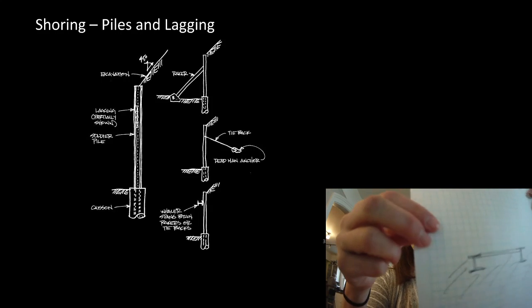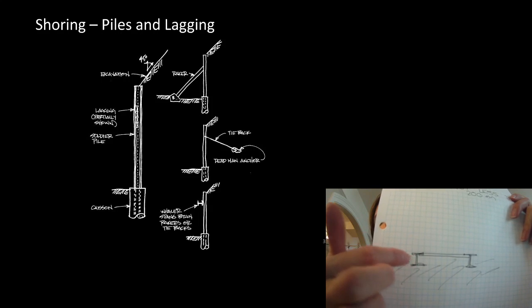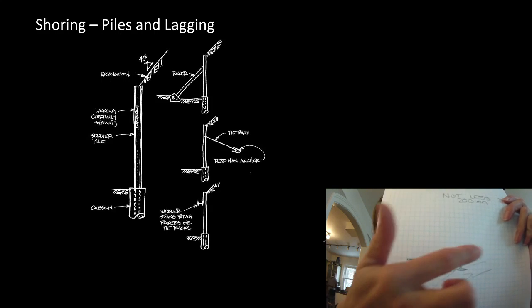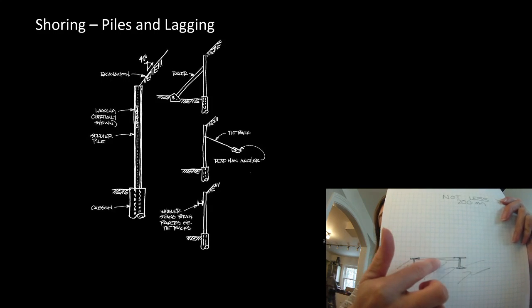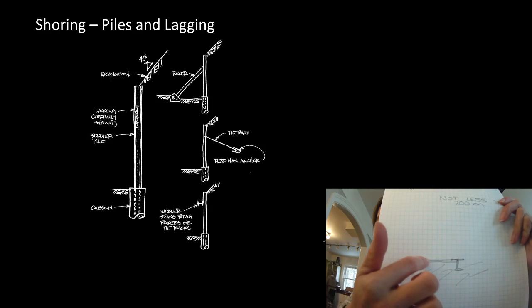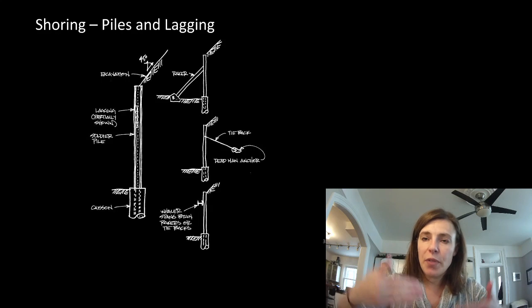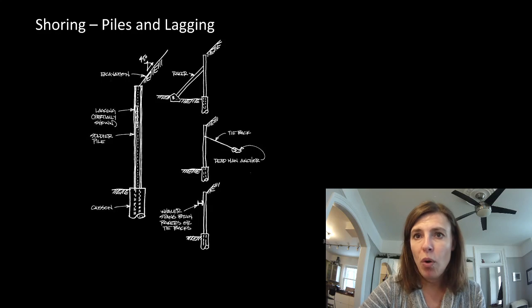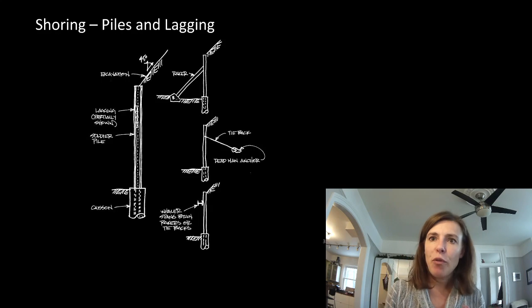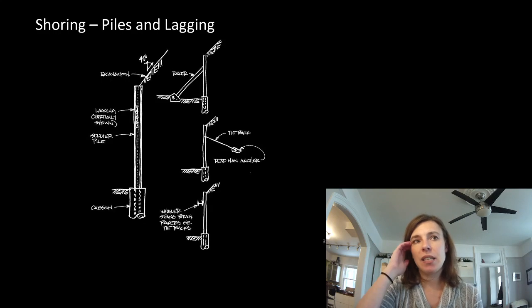It's disturbing. Okay, so imagine that they drive these steel members into the ground, and then they excavate 4 feet over here, which you're allowed to excavate with no restraint, and then they drop these pieces of wood in. And then they dig down 4 more feet, and all of those pieces of wood drop down with it, and so you're left with 4 feet at the top, and you drop more wood in. And then you dig down 4 more feet and drop more wood in. And so you do that again and again until you get the excavation you want.